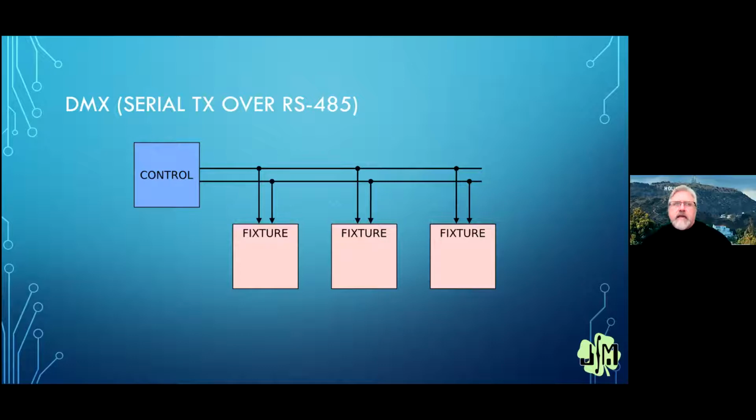There is another variation of DMX called RDM that I've looked at a little bit. I've never actually worked with it, but it uses the same hardware, but RDM uses a different start byte. The idea is that modern fixtures that see a non-zero start byte should just ignore the packet because it's probably an RDM message to one of those fixtures, and then that fixture can send a message back to the controller.